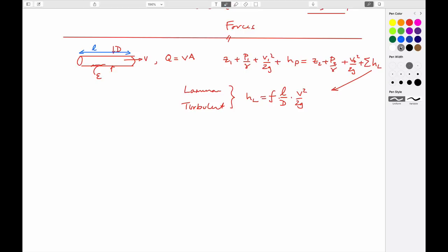And we know that when we look at these behaviors, we typically use a Moody chart to be able to reconcile response that gives us values for a Reynolds number, which is a velocity, a characteristic length, which is usually the diameter, and the density of the fluid divided through by the viscosity. And this friction factor, both of these are log scales, typically in Moody. If you need it in the test, you'll be given it, so you don't necessarily have to bring it along.